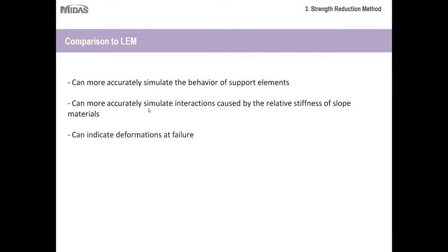It can indicate deformations of failure. So for whatever reason you want to simulate what your slope will look like or how it will deform, then you can do that with a strength reduction method.